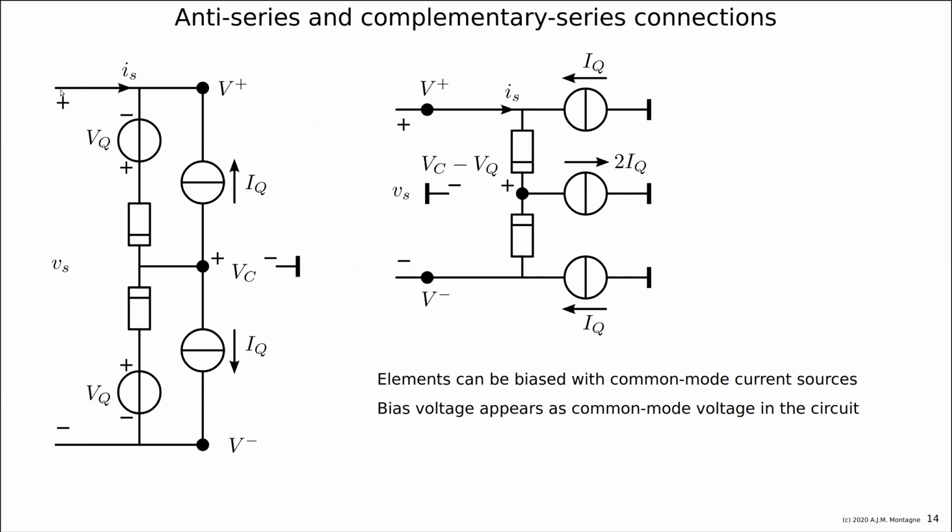If we apply an external current through this device, then through one device the current would increase, while through the other device the current would decrease. So both are coming in another operating point, having other derivatives, having other small signal resistances.